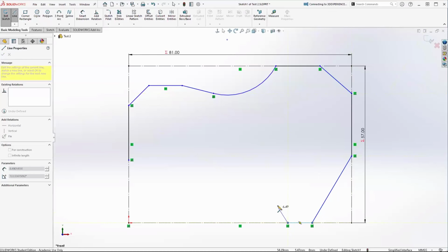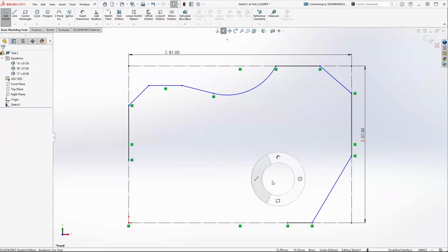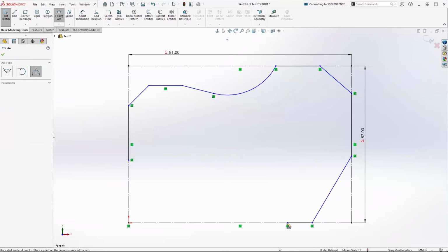And then here, this is where we're actually going to have two arcs, but because they're different types of arcs, we're actually going to do the S key and we're going to change it to a 3-point arc. Now, this one's a little tricky. The center point of this arc is actually on that right line, but a little trick. If you move to the center of a 3-point arc, it's actually a lot easier to control and move. If you go to the outside edges, it's actually harder.